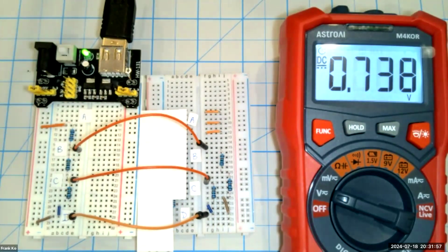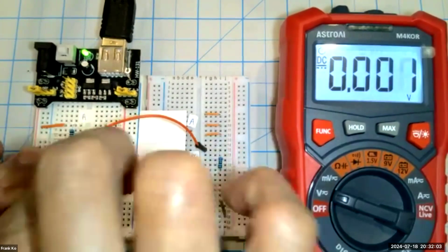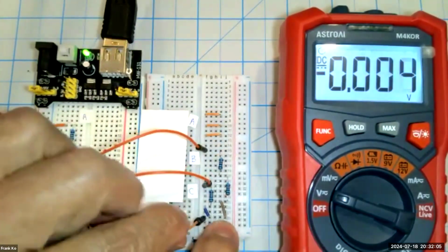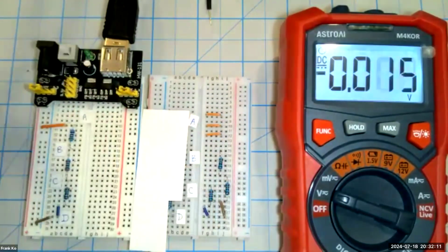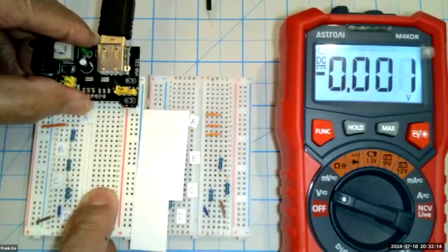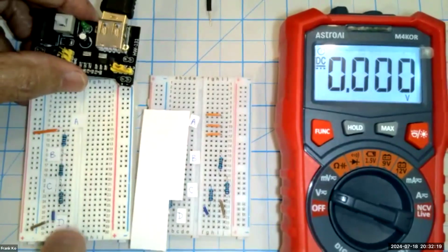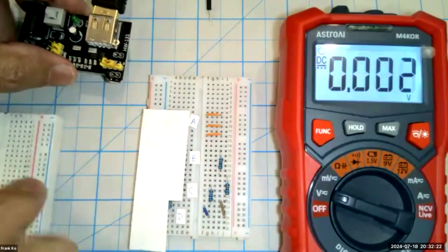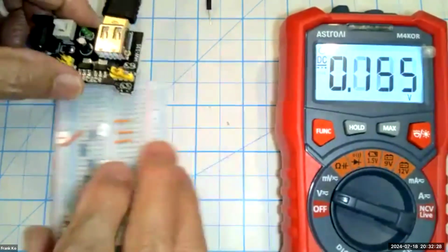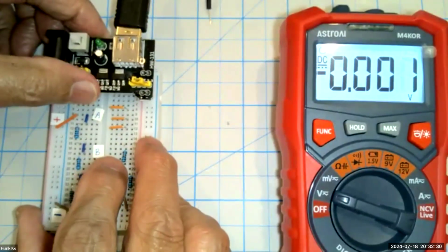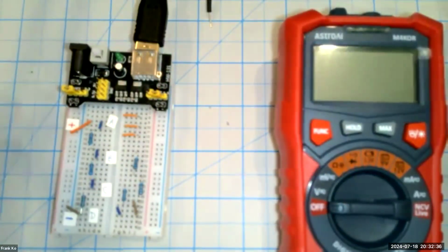So what that looks like, my friends, is I'm going to go yank this jumper out, yank this one out, yank this one out. And then on this side, yank this out, yank this out, yank this out. Turn off my power supply, detach it, set this aside because the original voltage divider is now useless to us because of the original resistor values. And what I've done underneath here is I've built the circuitry with the new resistances that we had determined would be appropriate.